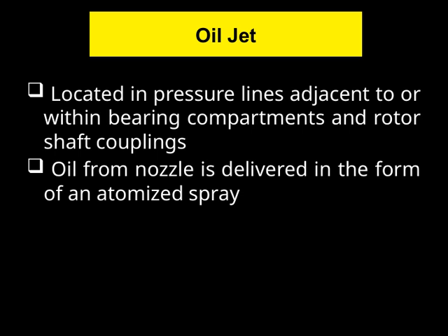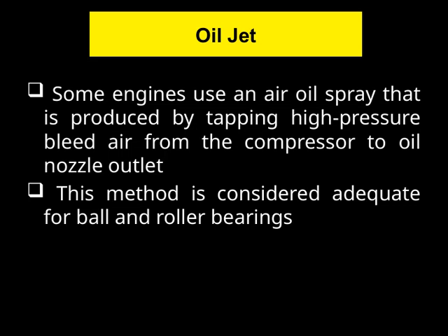Some engines use an air-oil spray that is produced by tapping high-pressure bleed air from the compressor to the oil nozzle outlet. This method is considered adequate for ball and roller bearings. Essentially, the high-pressure air helps atomize the oil, creating a fine spray that can be directed precisely where it's needed. This technique ensures proper lubrication without excessive oil consumption.